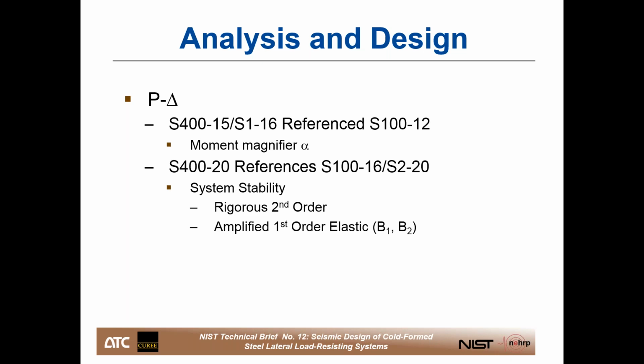And another interesting point about this amplified first order elastic analysis to keep in mind is that this is not just for design of the chord studs, for example. These are real effects in the system. So if your amplified first order analysis or your rigorous second order analysis determined that your uplift forces at your hold downs were elevated by a certain amount, for example, you need to design for those forces because they are real. They're not just a means to over design something to make it kind of work. They're actually forces that are anticipated in the structure and need to be addressed.